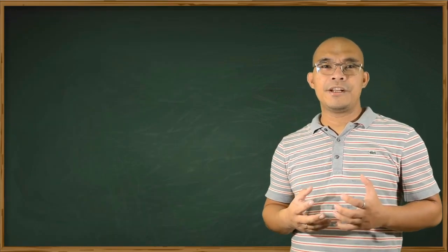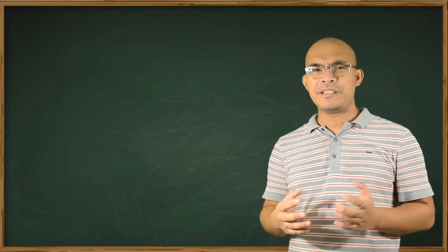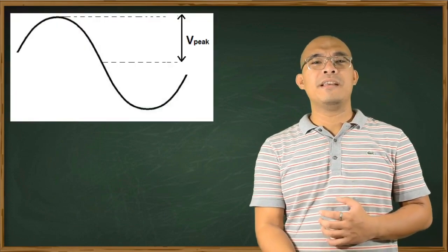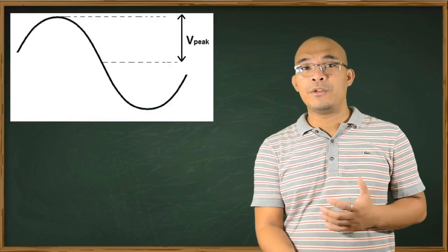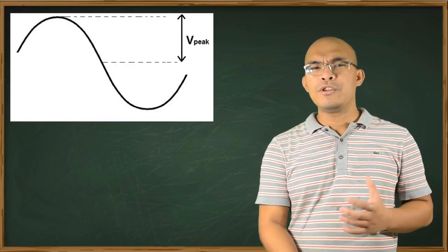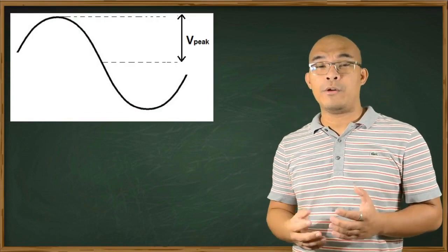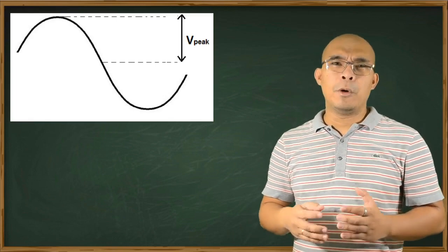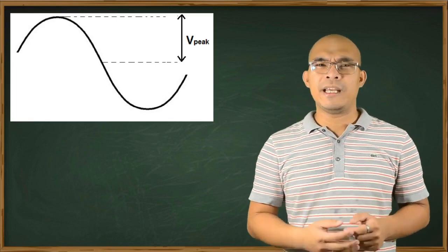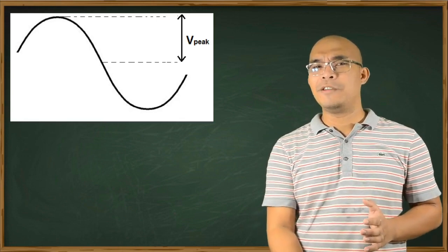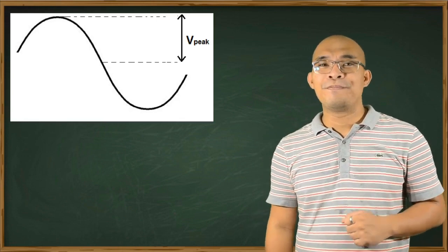An alternating electromotive force, or EMF, which ideally has a sinusoidal waveform, is induced into each stator phase winding. The useful EMF level is called the root mean square, or RMS value. The voltage that you can measure with a multimeter is an RMS voltage, while the peak voltage can only be seen on an oscilloscope.